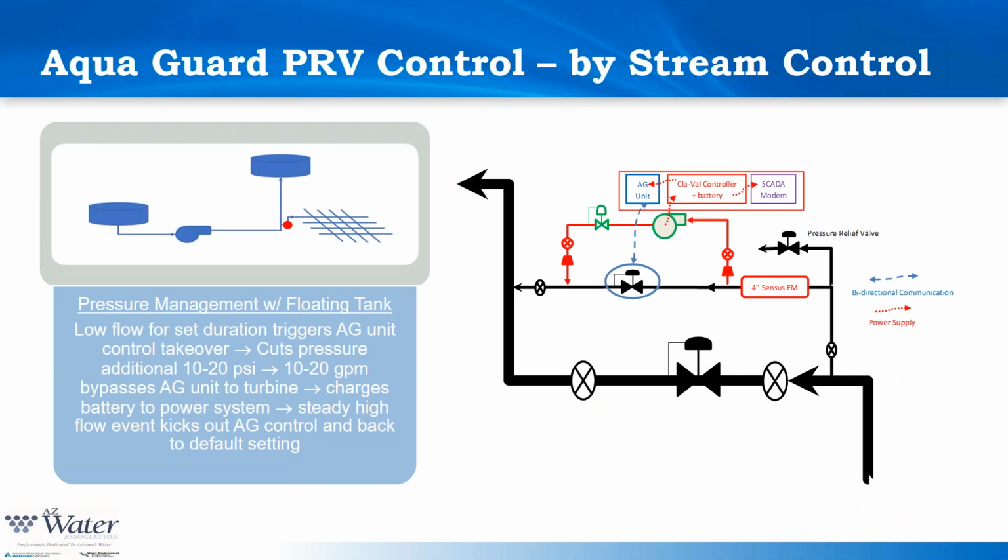This goes on the low flow PRV, which tends to be the higher pressure setting. The other parallel high flow PRV, the bigger one, is set at the lower pressure setting. Whereas the smaller PRV can't keep up and the pressure keeps dropping, and then the big boy opens up, and we don't care about that one because we don't want to decrease pressure at that point. There's some event that needs to be consistent. It's typically the low flow nighttime PRV, it takes over.